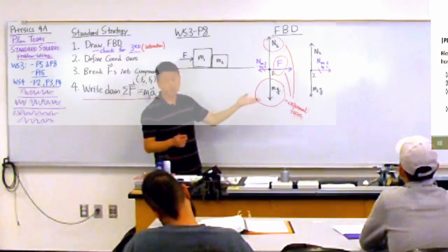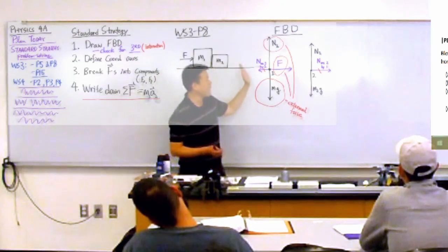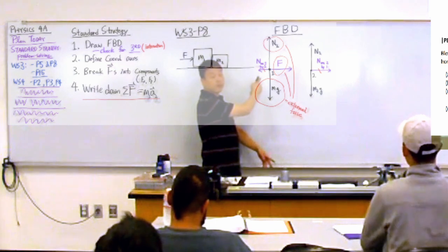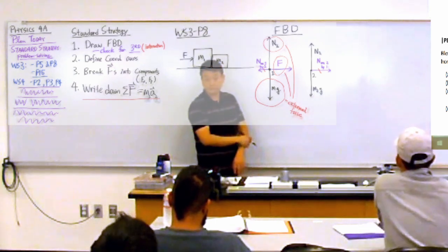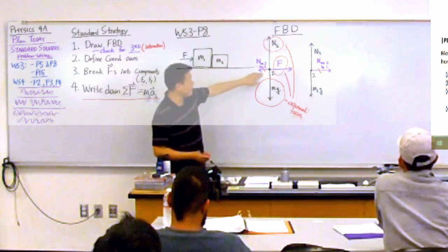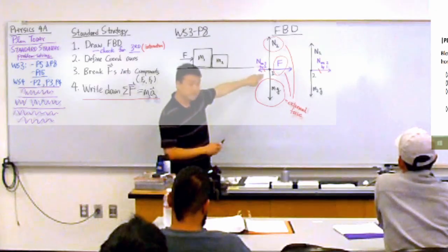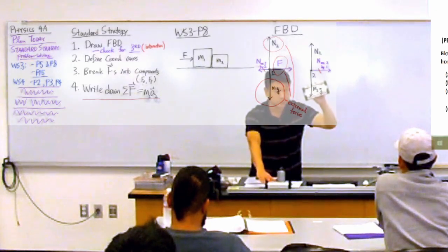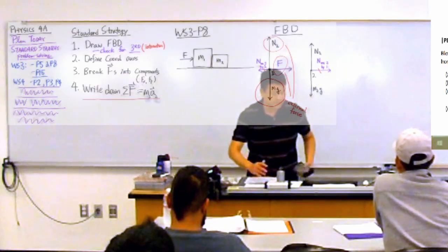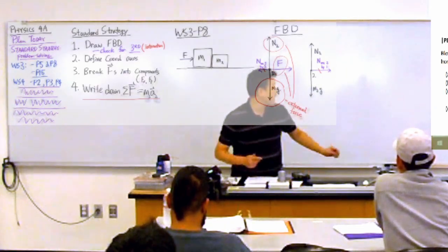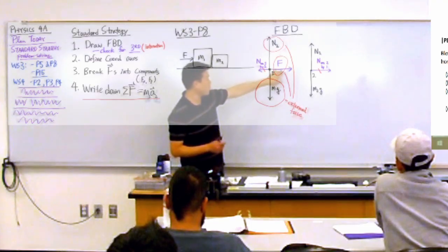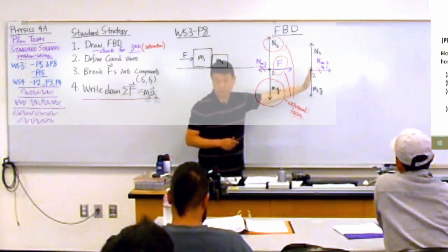So this is the Newton's third law check. It's going through your diagrams all over again, making sure that where a reaction force is required, you have labeled it. And you will see this in the math too. This force is why the mass of mass 2 matters. Because if I didn't have this mass at all, then for the free body diagram for mass 1, I wouldn't have this force. So this entire force will go into accelerating M1.